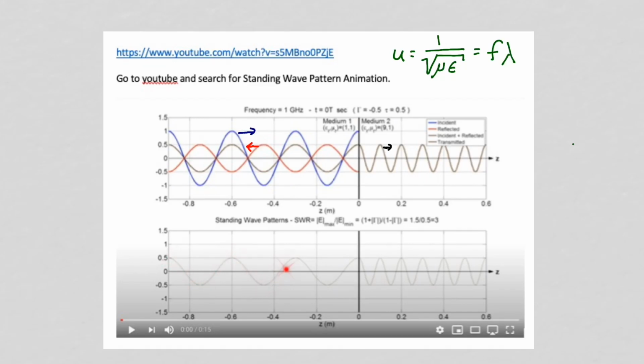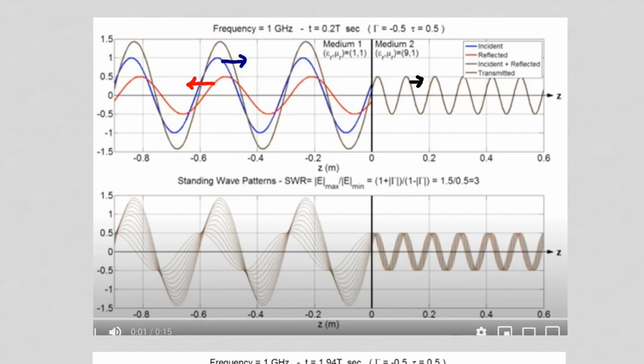Depicted in the bottom half here is the total electric field intensity in material 1 and material 2. As you run the animation, the total electric field intensities in material 1 and 2 will accumulate. So essentially taking a picture every delta t and superimposing all those pictures in the bottom part of the figure here. This would be the situation after the animation has run for a while and you've taken about a dozen such snapshots. So in material 2, this would be about the distance that the wave will have propagated.